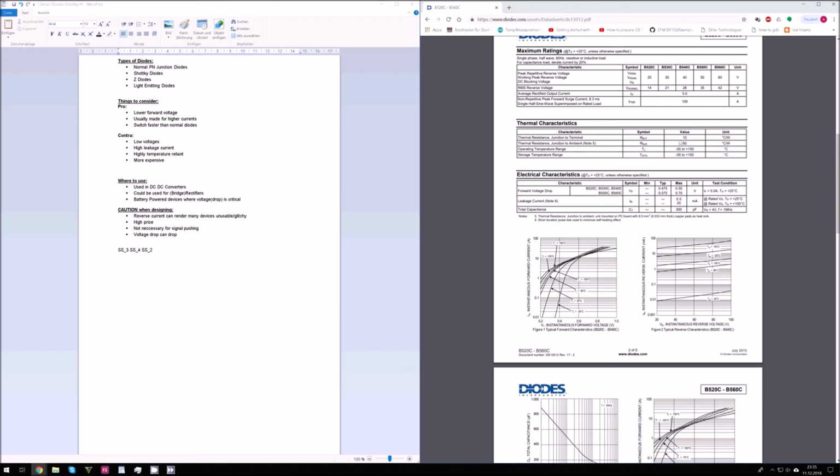If you don't have extra thermal things taken into account, consider this value, and make sure that at an environment temperature of about 40 degrees, your junction should not go over 90 degrees Celsius, so you should not drop more than 1 watt over this diode if there's no extended thermals, or if you don't want to risk heating up the diode to 120 degrees at its junction.